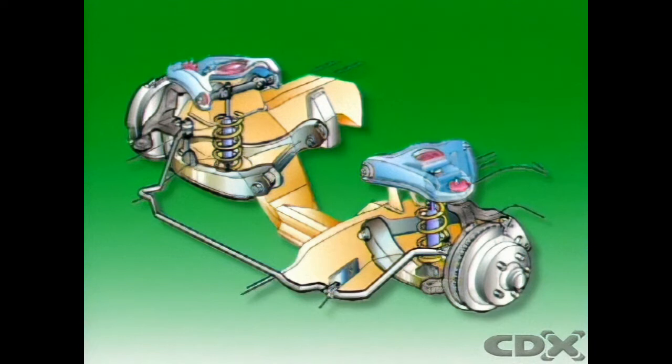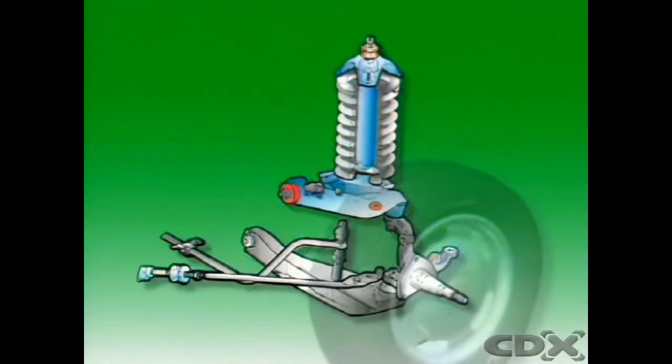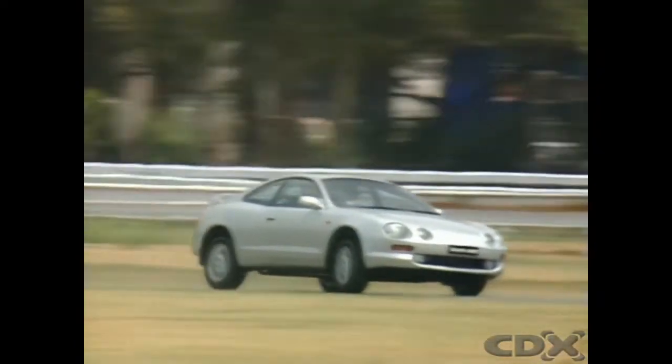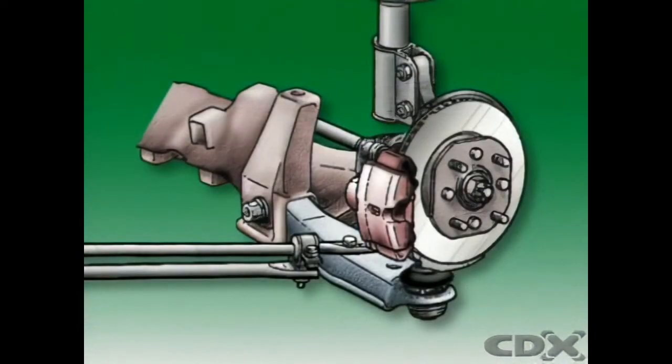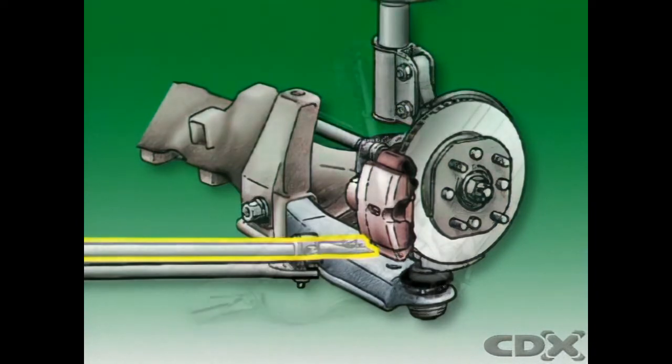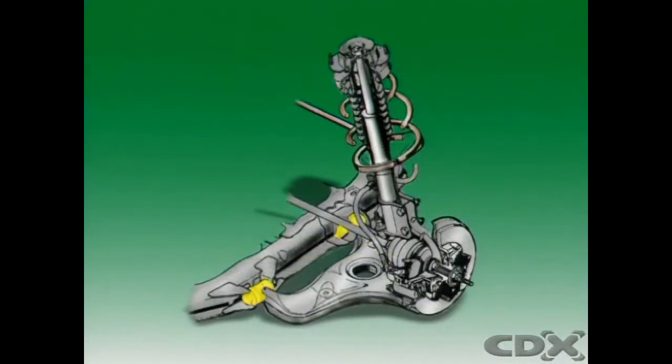Since the front wheels perform most of the braking, the wishbone pivots are widely spaced to sustain the braking torque. With a single arm, an angled bracing strut is needed. It locates the arm at its outer end, and during braking, it prevents forward movement and rearward movement. Similarly, during acceleration. In front-wheel drive vehicles, the driving thrust from the wheels pulls the vehicle along the road. This additional force is generally accommodated by more substantial bracing, or by setting the pivot points on wishbones further apart.